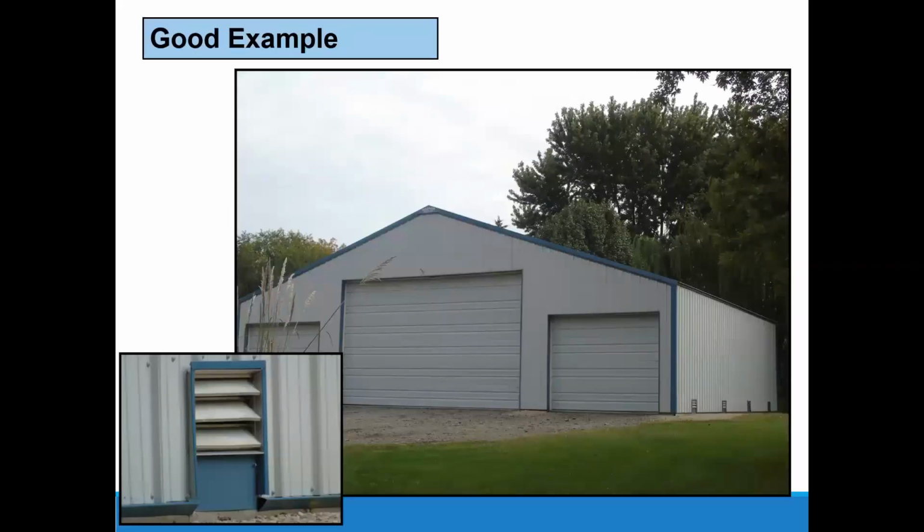This has flood openings. There is no size limitation on agricultural structures, whereas the accessory structures have that 600 square foot limit. And then this would be certified that it has the floodproofing materials. Obviously, any utilities would also have to be elevated and be on an elevation certificate. But otherwise, it could just have a permit and a variance.